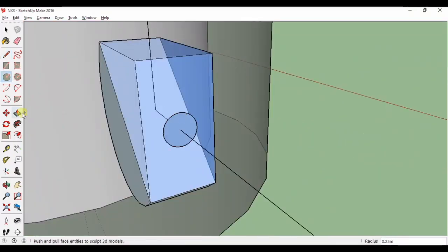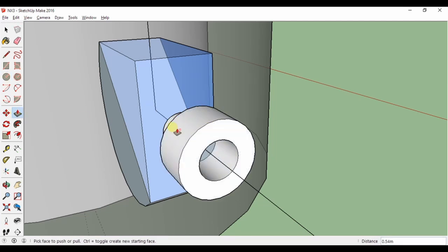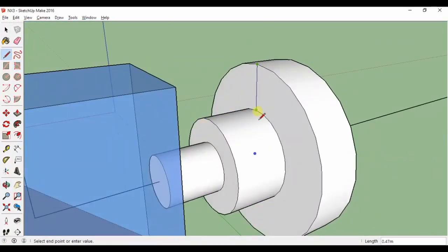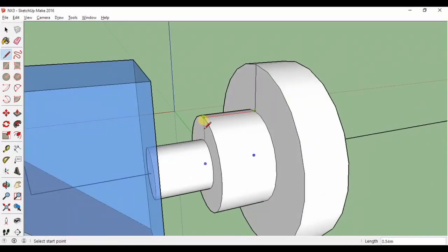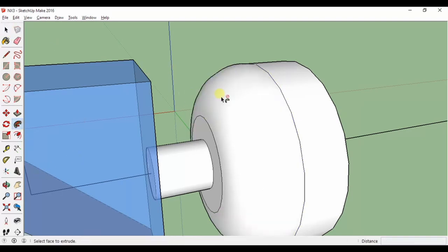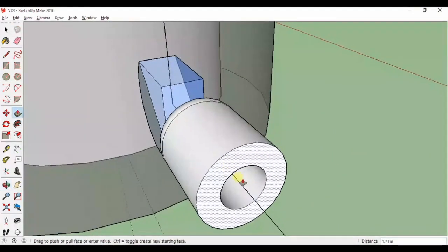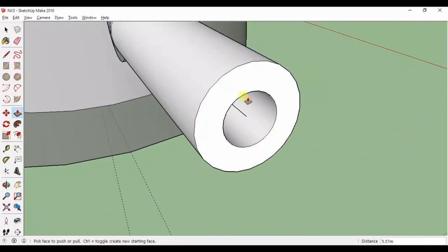Time to draw the laser in. I'll start by drawing the cylindrical housing. The front of the laser will be represented as a series of concentric cylinders, so it's a simple matter of using the Circle tool and the Push-Pull tool, but I can also add a bit of detail with the 2-point Arc tool, Line tool, and the Follow Me tool. A procedure similar to making the lathe part for the rotating mirror. Now for the body of the laser, it's simply one more concentric layer, Push-Pull, and then aligning the end of the laser beam.